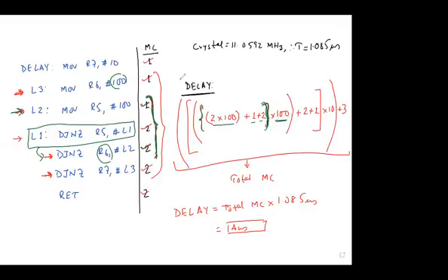Then you extend this same logic. What are the next two extra machine cycles? This machine cycle and this machine cycle, because this line controls the label over here. So we simply write extra 2 plus 1. Now, how many times will this loop run? It will depend on the value of R7. What is the value of R7? 10. That's why now multiply this entire thing with 10. Then you will see that we only skip these two machine cycles. So 2 plus 1 will give you 3. Whatever you get, that is your total machine cycle.